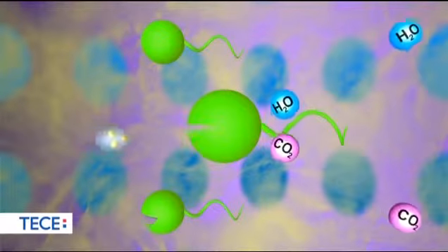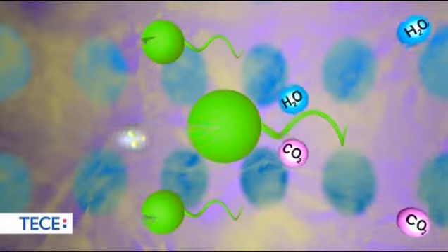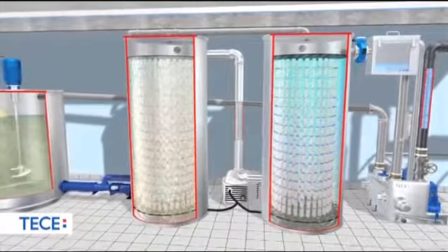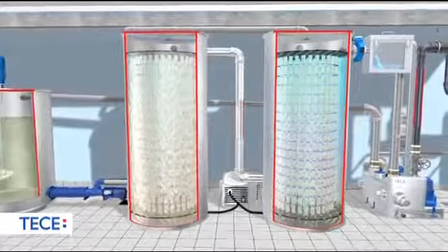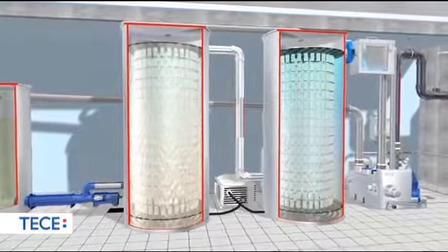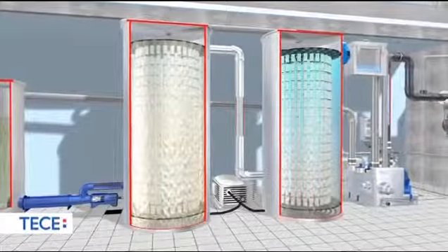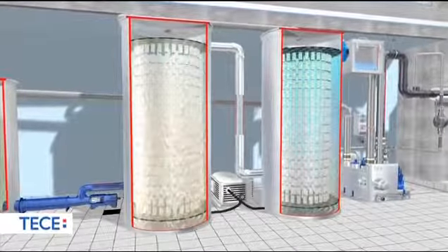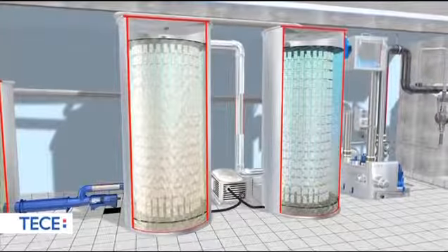The microorganisms used in the process are optimized with respect to their ability to break down specific substances such as grease, oil, and tensides. In order to efficiently break down fats, periodic alternation takes place between aerobic aeration phases and anaerobic resting phases. Oxygen is introduced using a separate compressor.